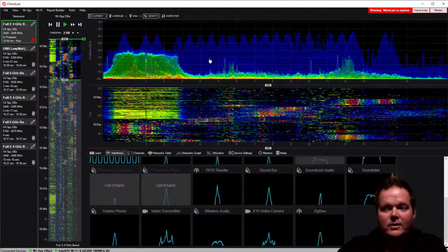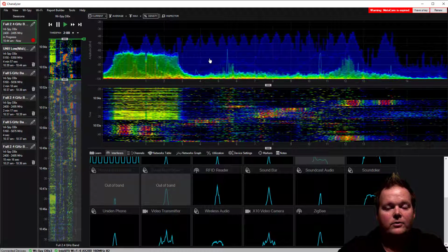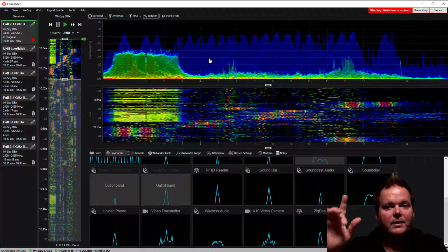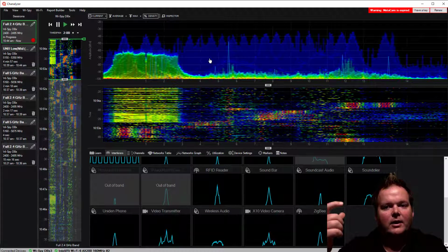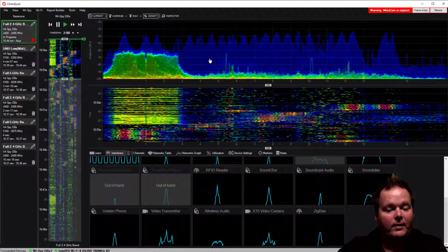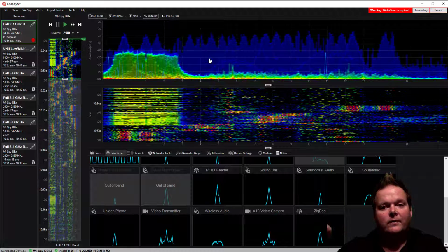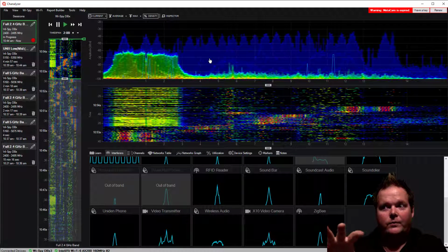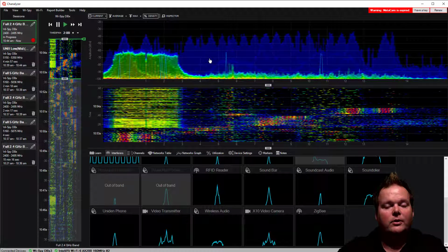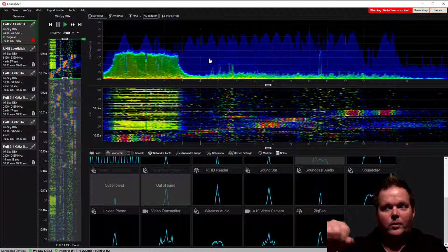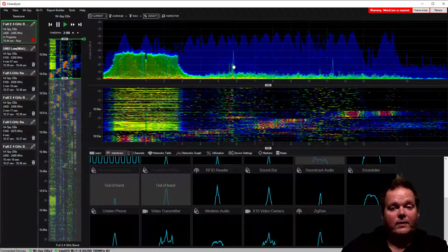So once I've got the signature, there's another tool you can use with MetaGeek to basically trace that signature, and it gives you a beep, kind of like a Geiger counter. So it'll go beep, beep, beep. And then whenever you found it, you know that's what it was that was causing the interference. Truly a great tool. And we use it for a lot of different scenarios to make sure that we're avoiding interference at layer 1. All right, we need to get rid of those devices, change them out.